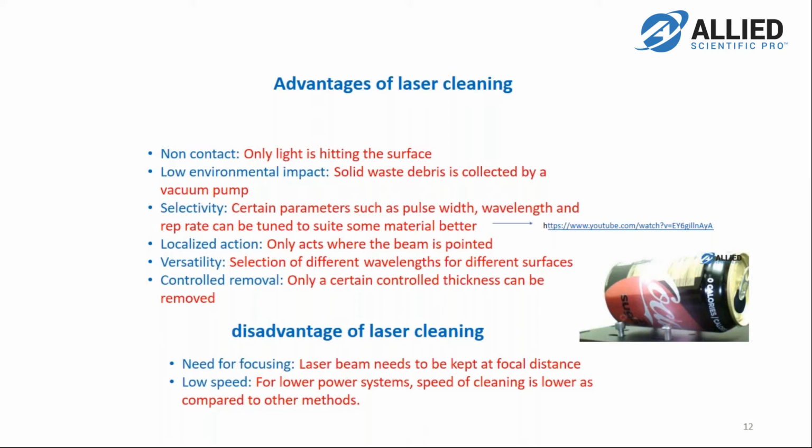So it's not like sandblasting where you can keep the sandblaster at any distance and pour that sand or grit on the surface. The laser cleaner has to be kept at the focal distance from the surface, and only then could it effectively remove the paint or the contamination.